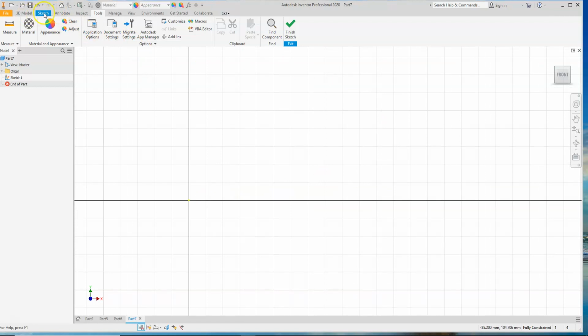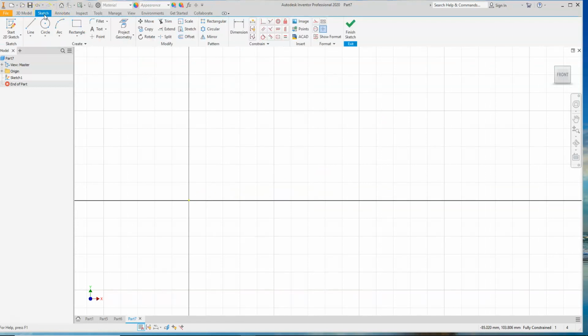So starting over on our sketch, I'm going to go back to sketch. I'm going to go to rectangle, and once again I prefer to start my rectangle at the origin, so I am going to make sure that I do that. I'm looking at my box here as I'm looking at my snap options, because that snap is there and it's clicking to it. You should see that your pointer should just snap right over to those every 5 millimeters. You should have it snapping.